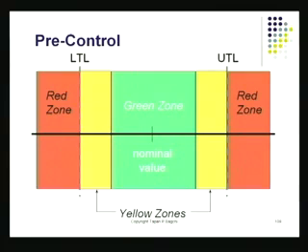If you do that, you'll maximize the visibility of the assignable causes, and you'll make sure that the base variation, which is due to the chance causes only, that also is apparent and is pure. Within a sample, you only see what we call chance variation. So just go into this a little bit with your statistics, with your SPC book, and you'll be able to probably pick up the thing.